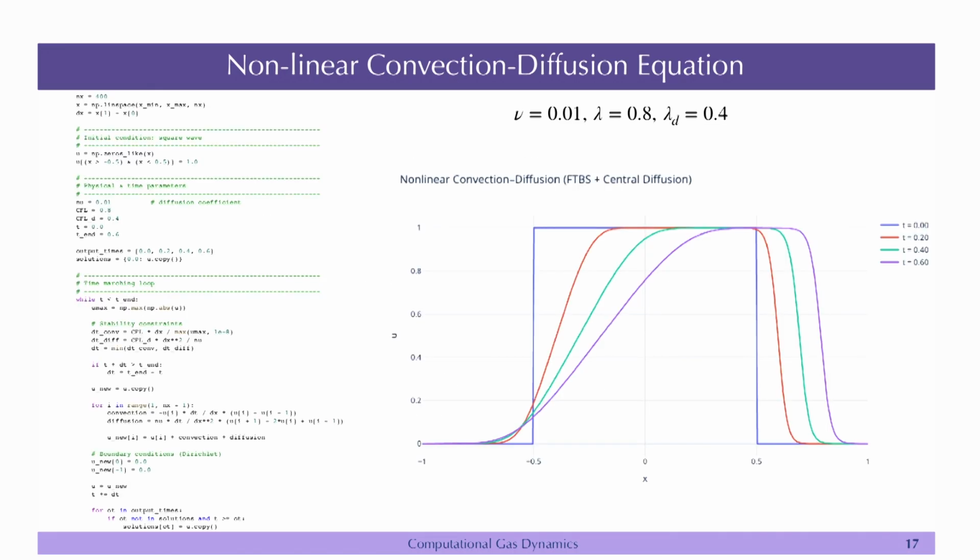And so, this is what I do here. Okay, so you can see that I have fixed the CFL 0.8, CFL d as 0.4, and then I calculate this convective time step dt underscore conv. So lambda equal to C delta t by del x. Now, C is given here, I think it should be specified somewhere. This is u delta t by del x.